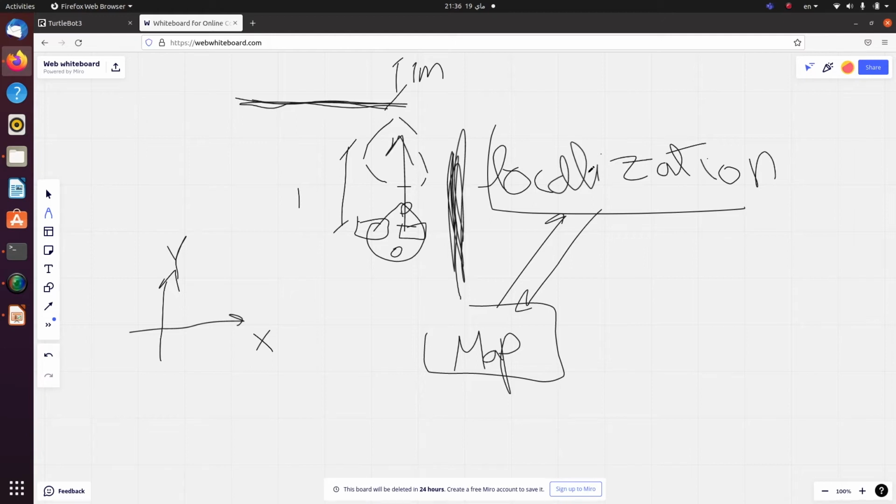So let's have an example where the robot is navigating and we've got our set of sensors. For example, the LIDAR sensor for update and some dead reckoning sensors like the encoders or the velocity. So what you do here is first you take a LIDAR shot, so you get a local map that's attached to the current location. The current location is unknown, so I just say that the current location, which was unknown, had a local map, for example, with this LIDAR shot.